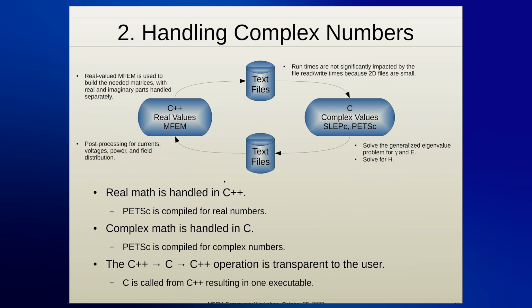Handling complex numbers, the most straightforward way I could find to do it was to do all the setup in C++ using real values in MFEM, then go to text files, then import those into C, where I would use complex SLEPc and PETSc, so that the total compilation has PETSc compiled for real with MFEM, and it's compiled for complex for the C program. Then when it's done solving, you go back to text files, import them back into the C++ program.